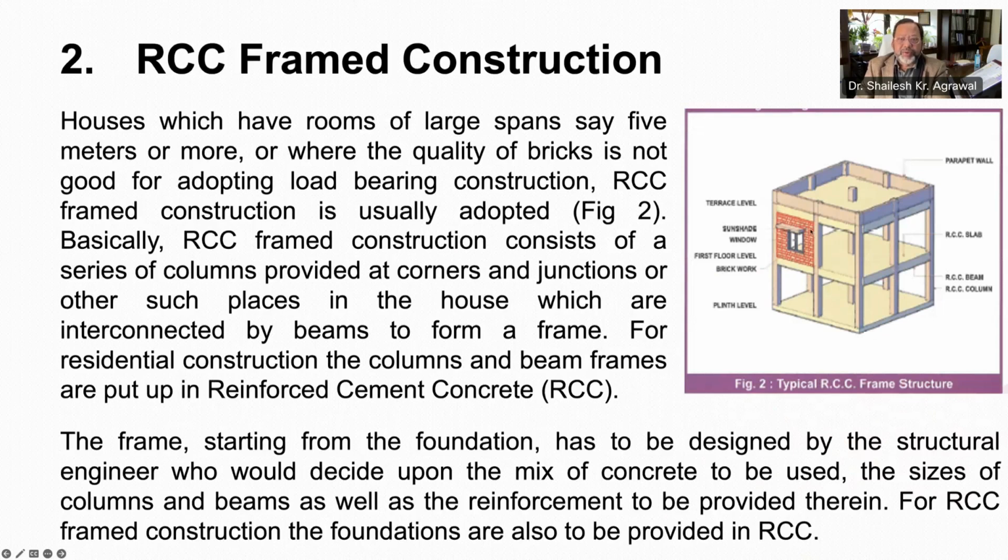The spaces between the frame are filled with bricks or other such material as may be required as per architectural details. These frames are RCC frames, and starting from foundations have to be designed by a structural engineer, who in turn decides about the mix of concrete to be used, sizes of beams and columns to be provided, and reinforcement details and its detailing.